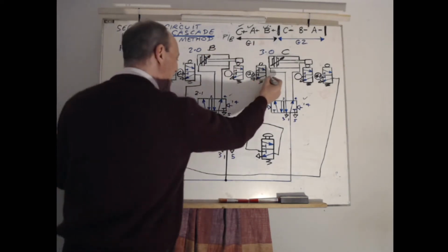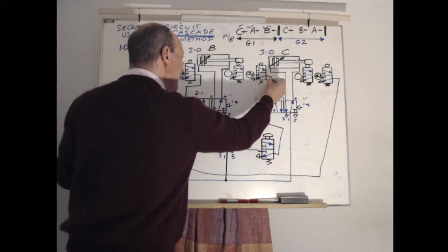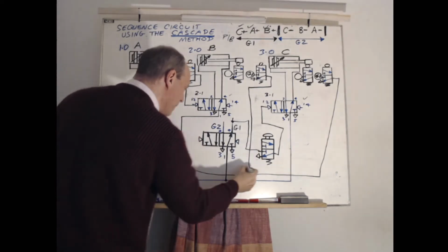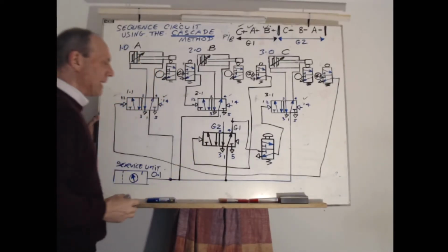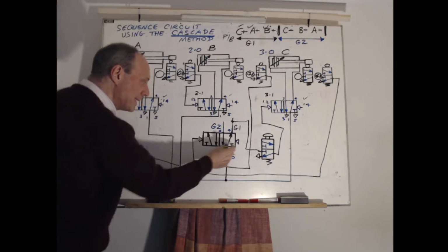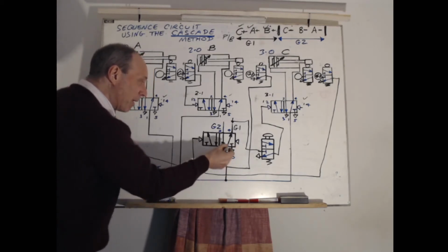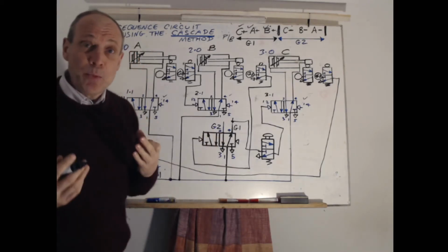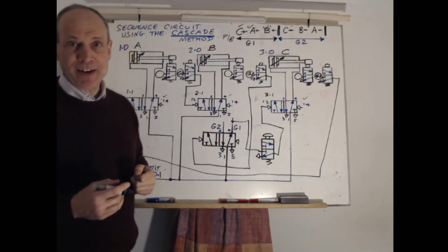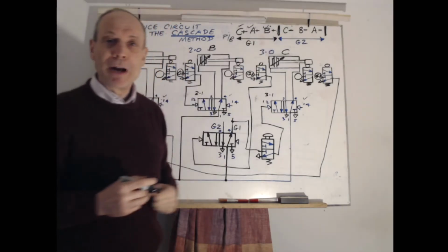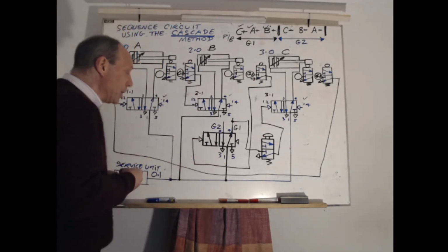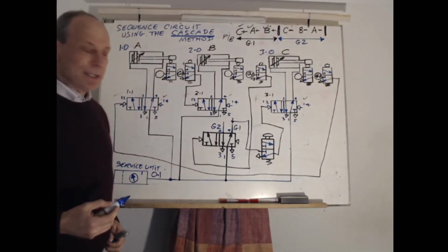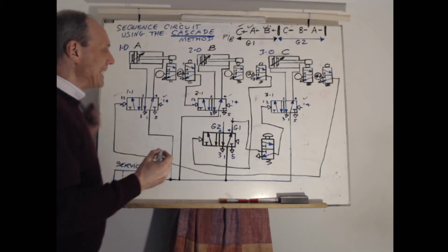So it takes the air from here and it feeds the air down, down, down, up, and to that side of the valve. So this valve goes across, and the air from this main supply is now going to go through here and out of G2. Therefore, all G1 has been sent to atmosphere, including what was the trap signal. We've now brought on G2A. So G2A can continue with this sequence. Its first operation is C minus.